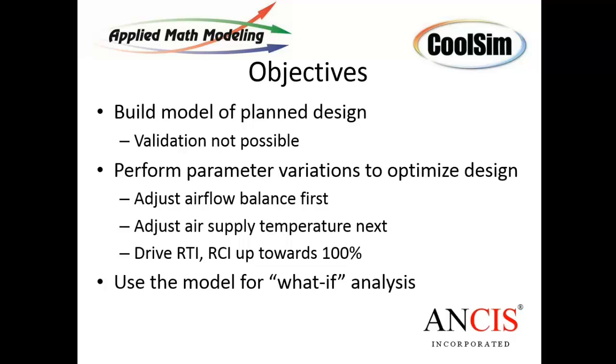If the data center already exists, it's important to build a baseline model and then go take a few measurements to make sure your model is predicting what the current situation is. And then, of course, you perturb it or change it to understand what it's going to look like under certain conditions. In today's examples, they're new designs, and so we don't have them built yet. This is both the beauty of CFD and in some cases the constraint.